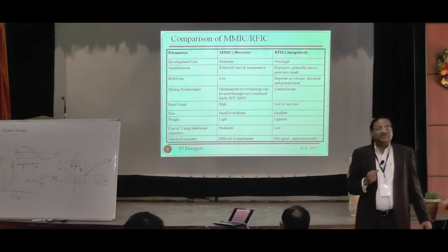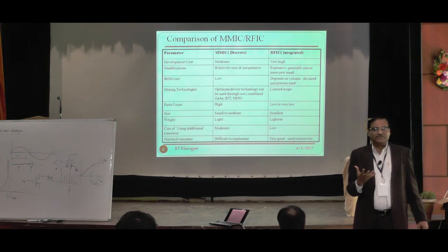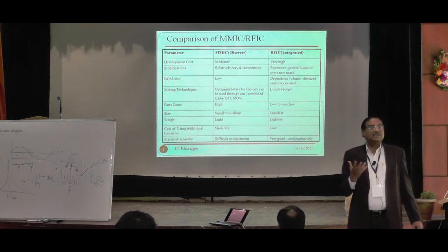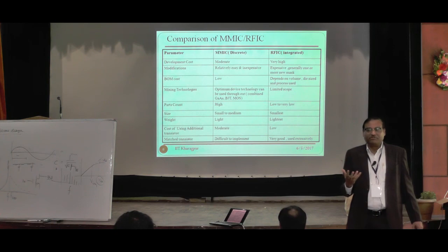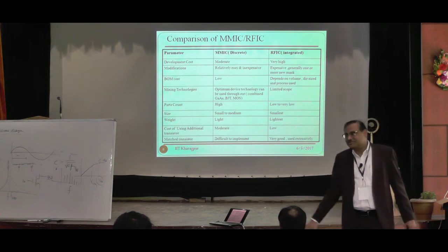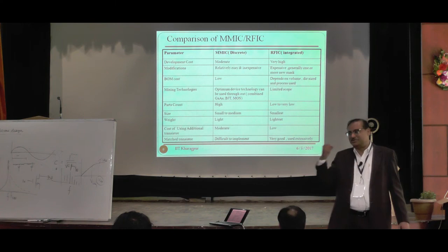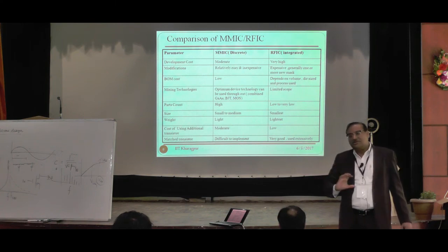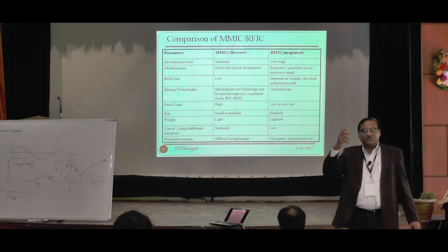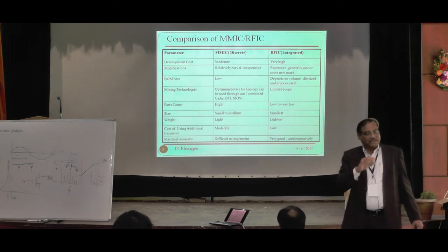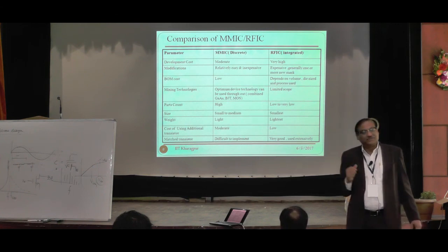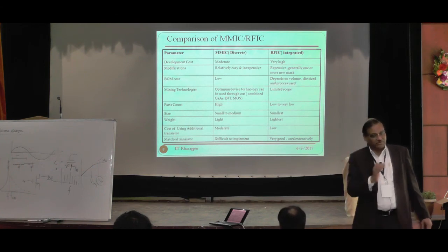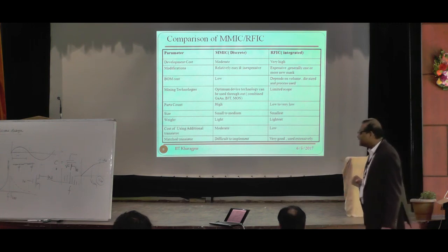But an oscillator, Barkhausen criteria tells you that you don't need any energy like that, but that is basically the ideal case. If you exactly satisfy the Barkhausen criteria, the oscillation build-up will last a few nanoseconds, after that the oscillation will stop. You need some additional energy to feed. So your A beta is not equal to 1, a little bit high. You remember the beta factor, right? That little bit high you have to give and then reduce it. So that's the story.